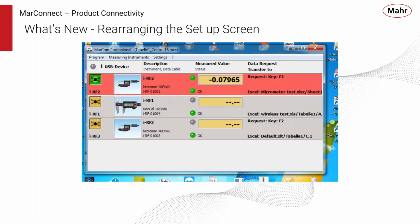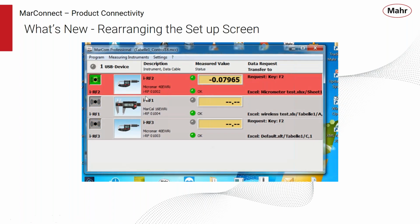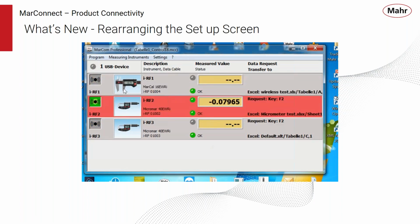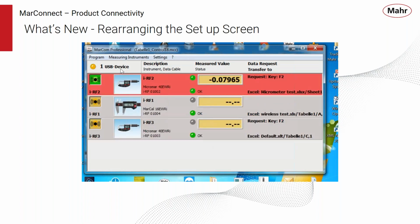We also have the ability now on the configure screen to rearrange the operations or the various gauges that are in the measuring cycle. And now, again, this is just a Windows feature which has been added to MarCom, where you can drag the device to where you want it in the gauging sequence. So, again, another small little feature that makes the setup a little bit easier. In the past, you might have had to delete and then re-enter a device through configuration, but now you can drag and drop that into the order that you want.